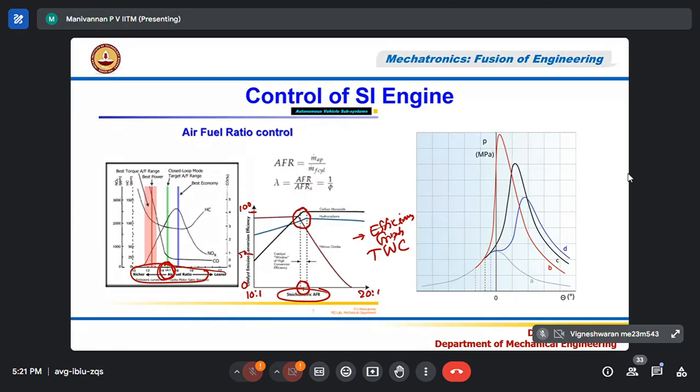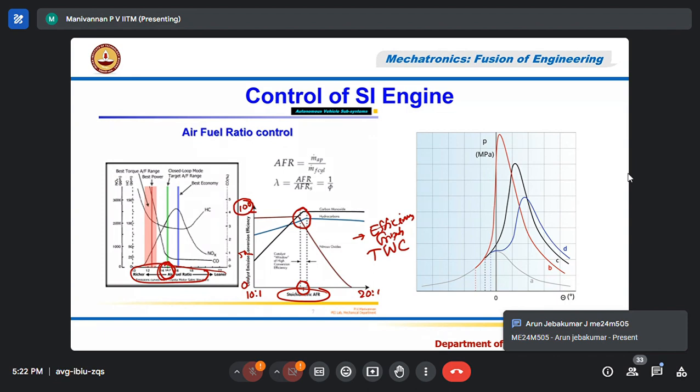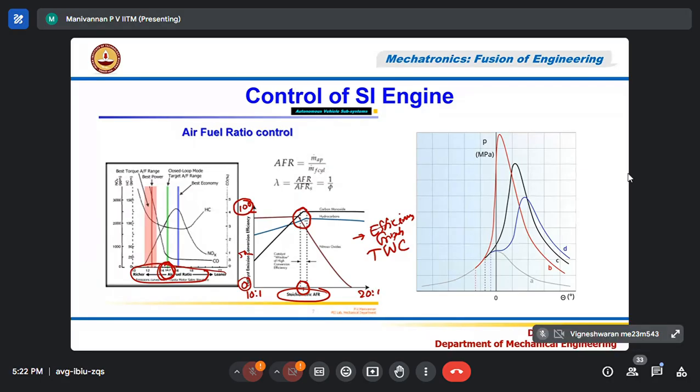50 means how much NOx, CO, HC are converted to H2O and CO2. If all are converted, I say 100% efficiency. If nothing is converted, I say 0% efficiency. The three-way converter conversion efficiency is maximum, and all three gases will convert to CO2, H2O only if you maintain stoichiometry. That's what it says here. You can see that very small band. If I maintain it, the conversion efficiency of all three gases, carbon monoxide, hydrocarbon, and nitric oxides, is around 90 to